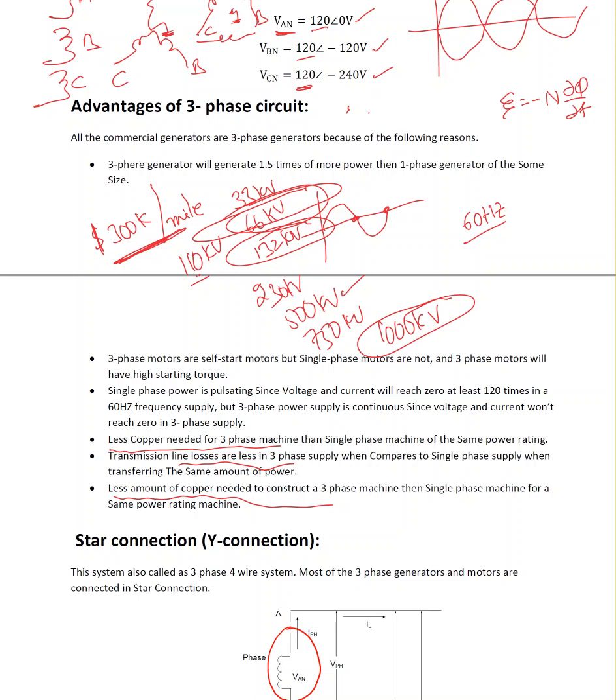Now when it goes to a 4-phase line of the same 66 kV: a 3-phase 66 kV line needs to carry only 3 wires, while a 4-phase line needs to carry 4 wires. So you are paying extra money for the 4th wire, and you also have to build a tower a little bit bigger because you have to maintain minimum distance between 2 wires, since all the wires are live wires.